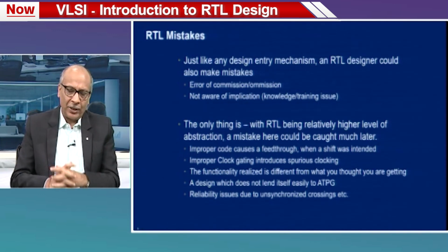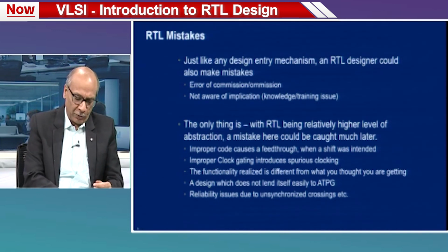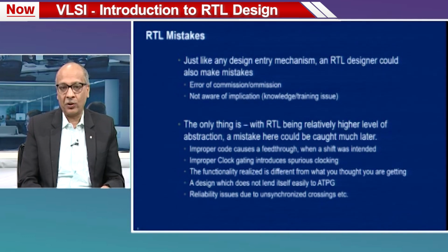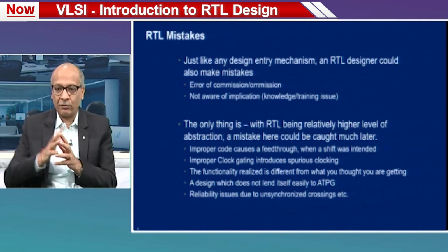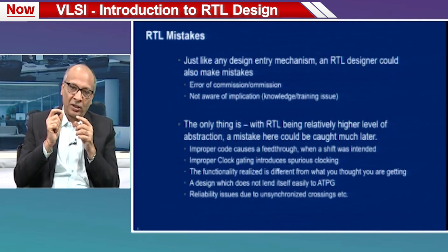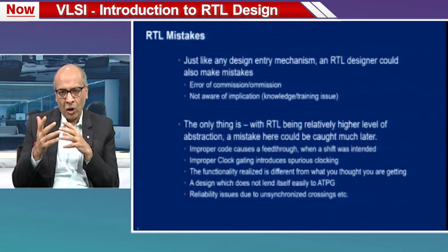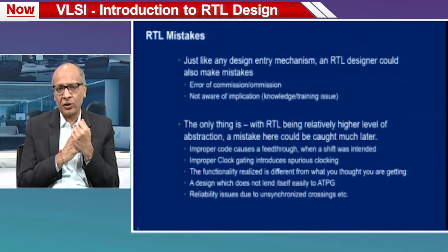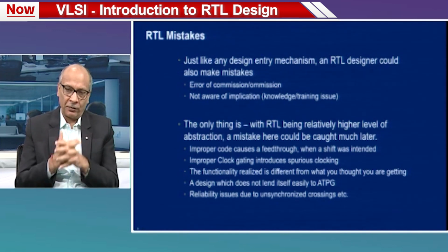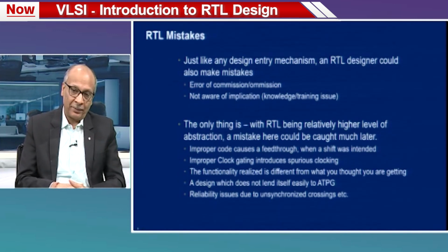Again, something that we should take care of at the RTL stage itself. And then there are reliability issues also. We will often hear something, and you may have also seen at your home some instrument does not work, you turn it off, turn it on and it starts working. These are because of reliability issues in those electronic instruments. Unsynchronized clock domain crossing is one of the reasons which causes reliability problems.